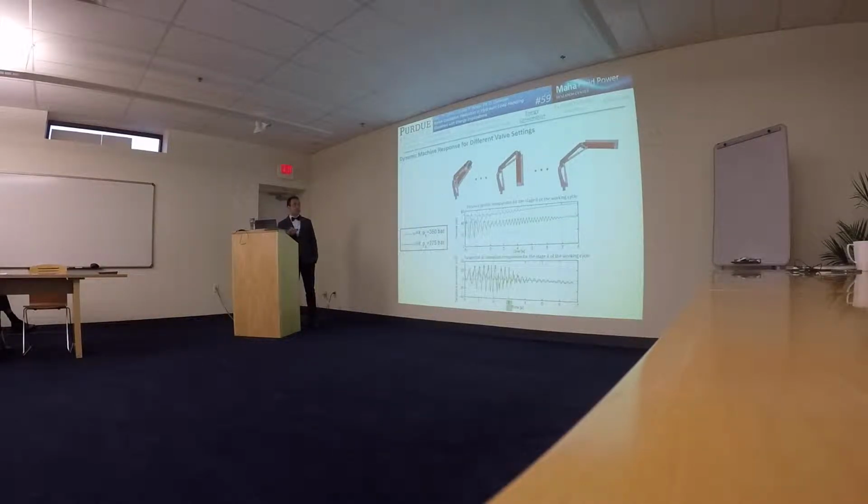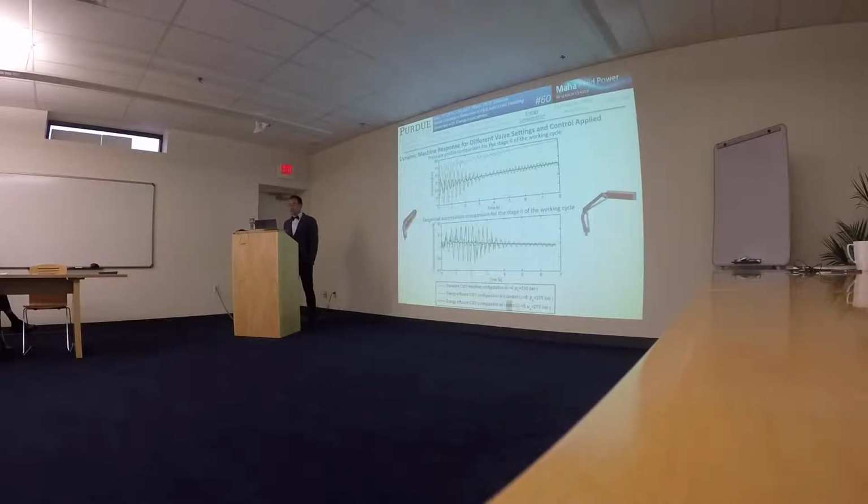For this particular operation, we can see the pressure profile in the first plot and the acceleration of the boom in the second plot, where I'm just comparing an energy inefficient setting of the valve with a good dynamic behavior, with a very efficient setting of the valve, but as you can see, a very excessive oscillation content of the motion.